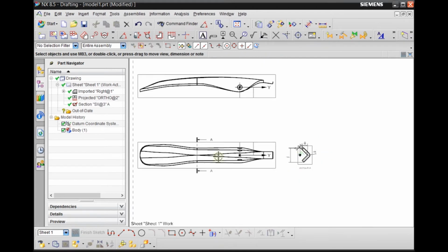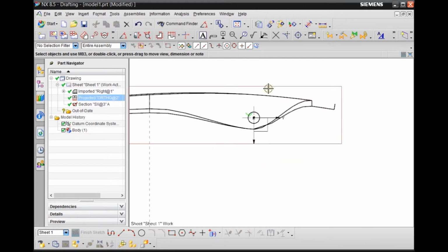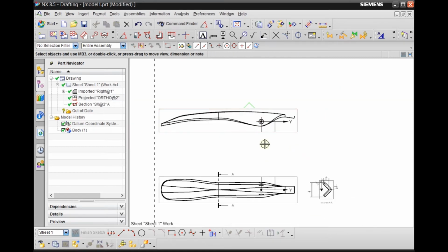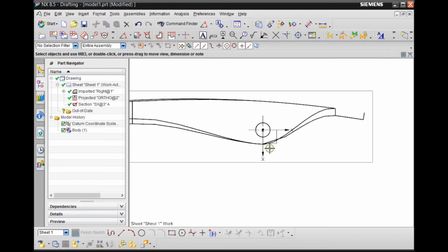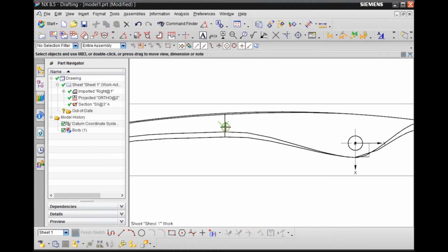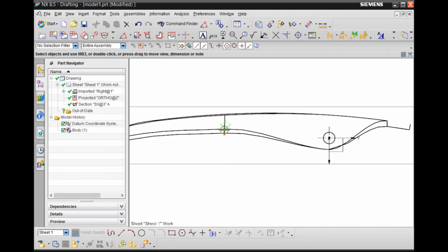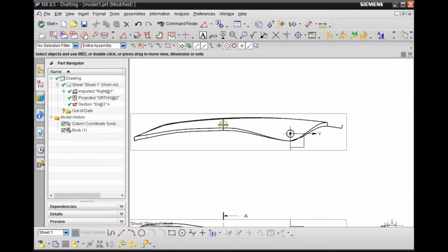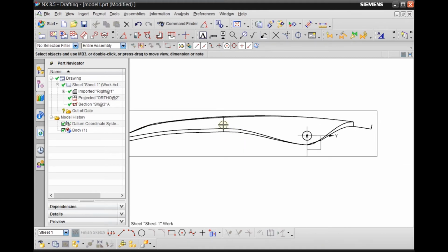Then you can do another cross section, and you can see from here that's your coordinate system. When you model this part, you can start from this coordinate system and keep measuring. These cuts are obviously from the IGS file, so it will automatically cut the surface.